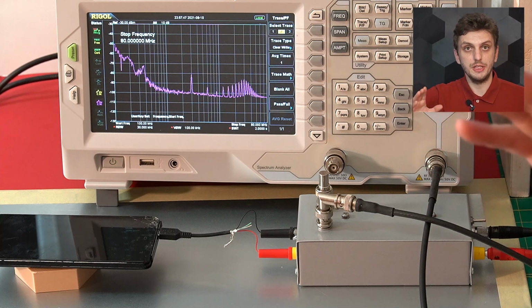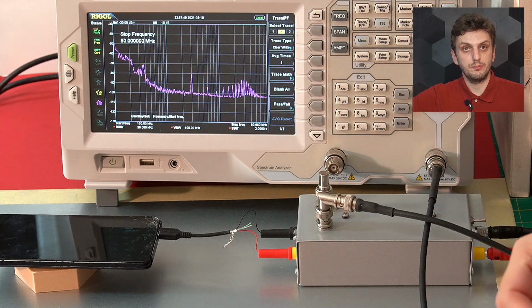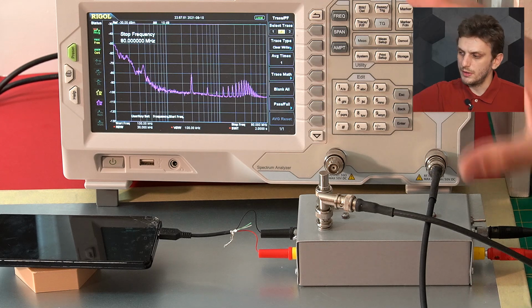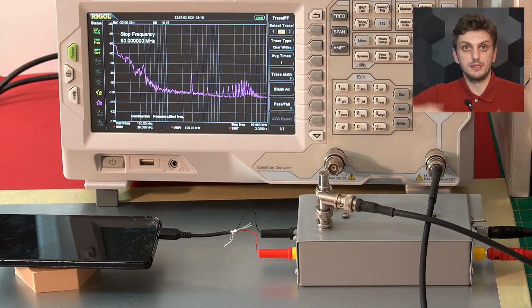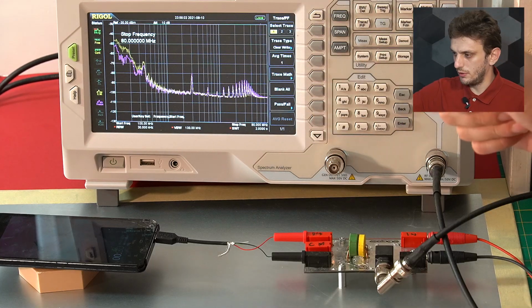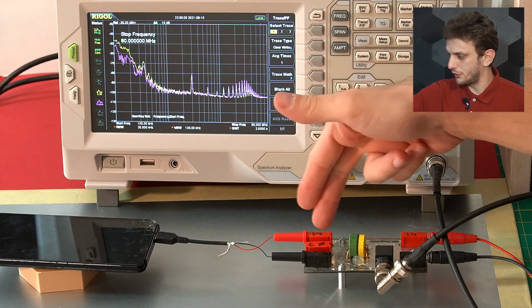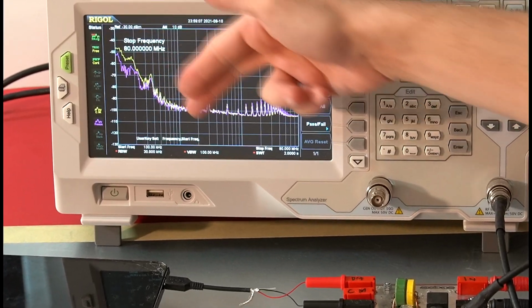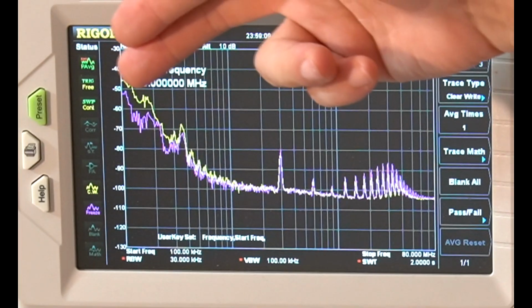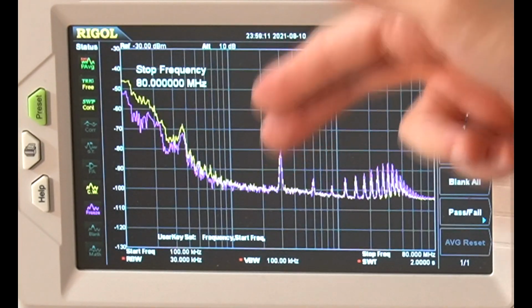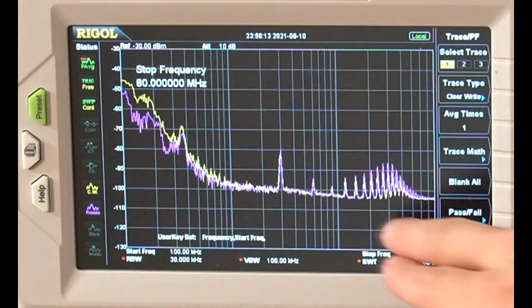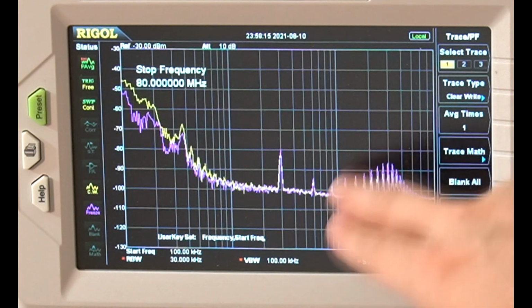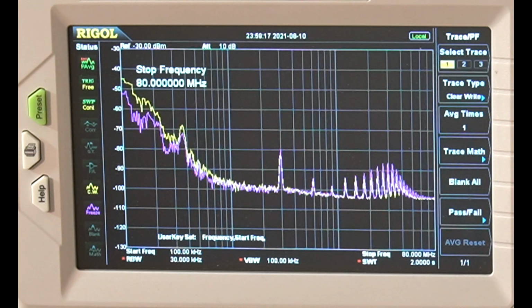So now I'll freeze it, and then I'll take out the separator to see what part of this noise is what kind. So first of all, I set it into the differential mode measurement. So we see most of our initial spike is differential mode, so is our 3 MHz spike, and then the differential mode noise starts to die out. So this high frequency stuff seems to have only a partial differential mode content.